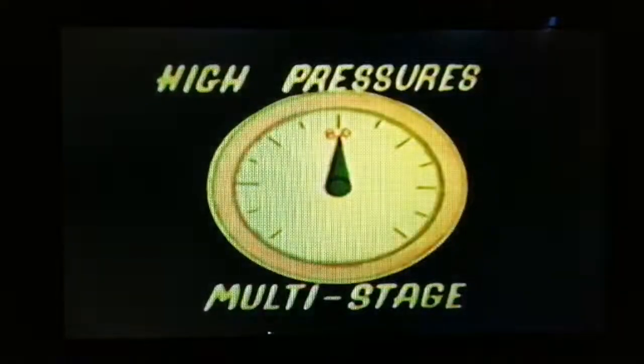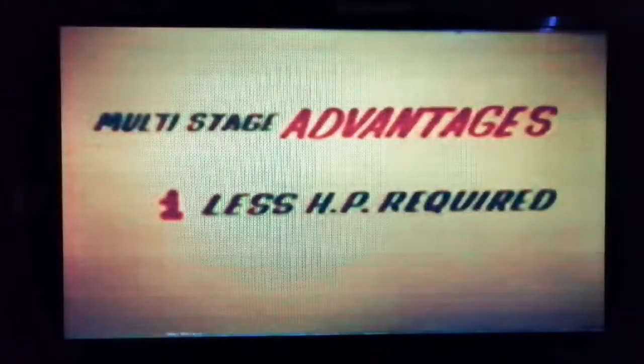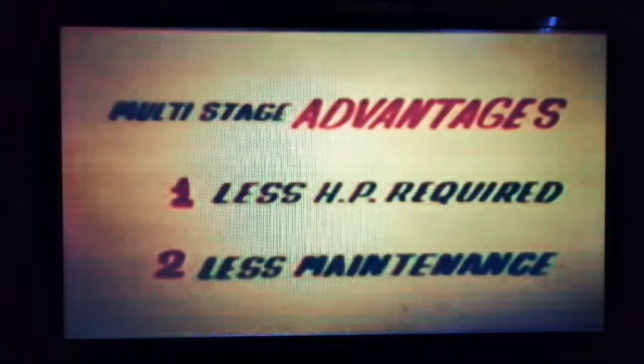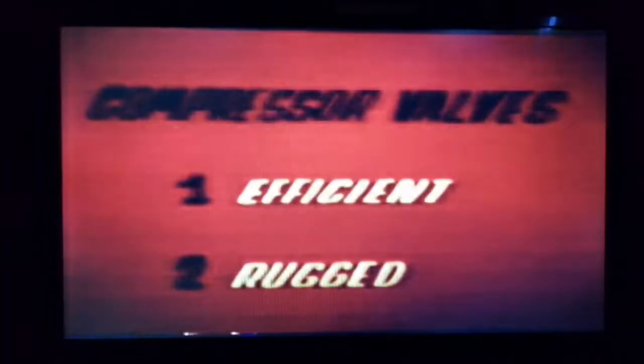For pressures above 80 pounds per square inch, multi-stage compressors are generally more efficient and economical. There are multi-stage compressors in operation which utilize as many as 7 stages. Another advantage is that multi-stage compressors require less maintenance because lower temperatures permit better lubrication and, of course, reduce deposits on valves. Valves are perhaps the most vital part of any compressor, and they must be both efficient, that is, they must function correctly and easily, and they must be rugged and long-lasting.